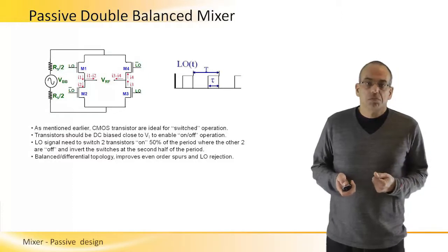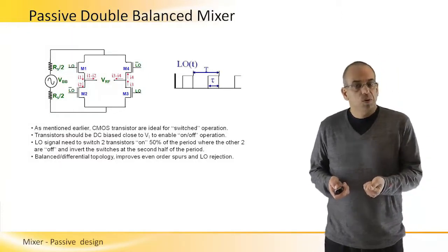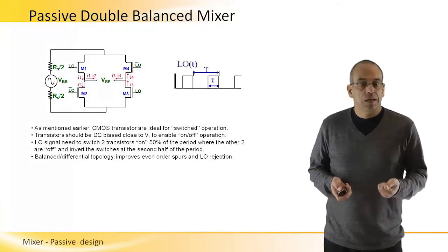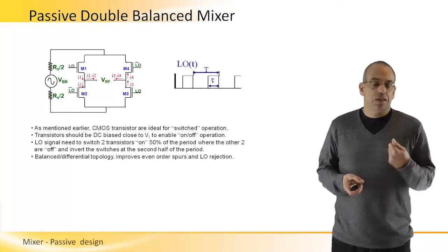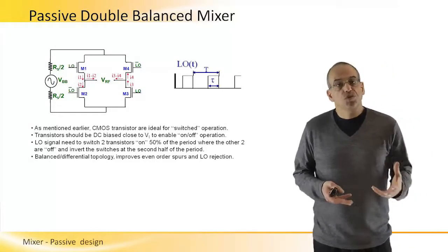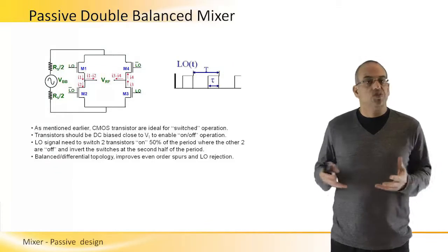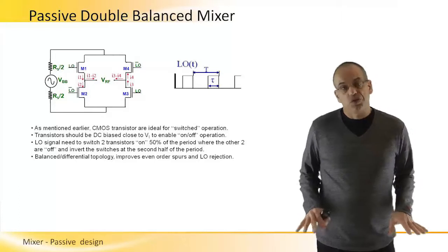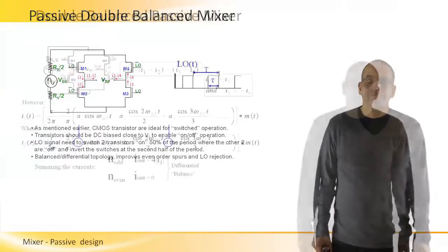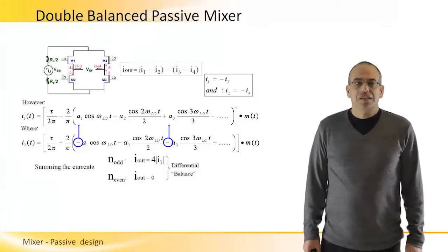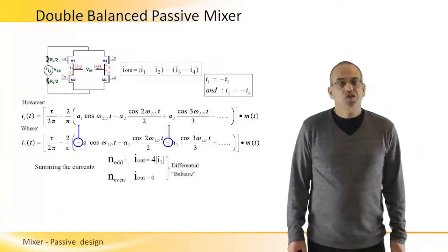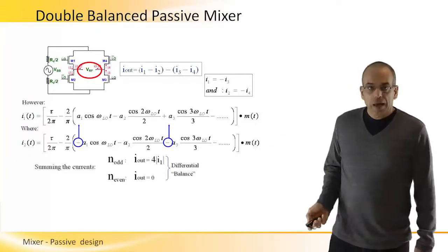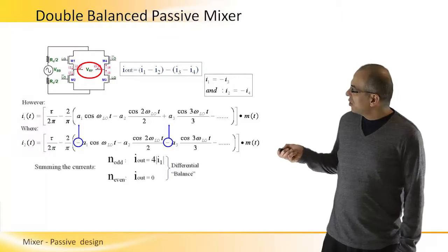As I said before, we will see soon that this balanced topology is a good way to improve LO, local oscillator, leakage to the output, and also to further reduce the even harmonics. Analyzing the performance of the balanced mixers, we need to look at the output, and we said that these mixers are current driven.